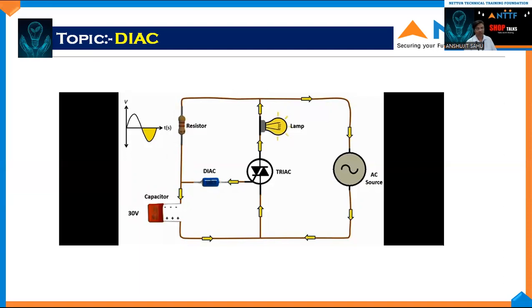Here we have seen that the diac passes bidirectional current. It is generally used with capacitors as here. In addition, the capacitor used here should in particular be a non-polar capacitor, because there is AC here and the capacitor must be used in both directions.